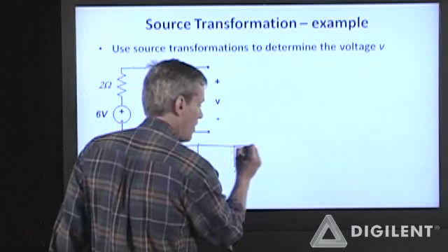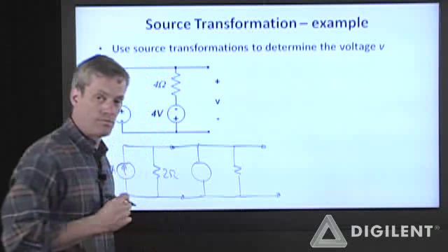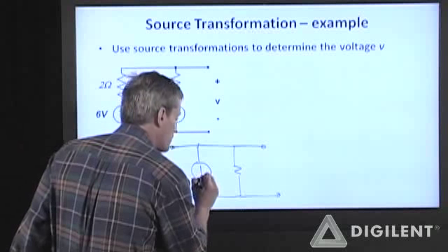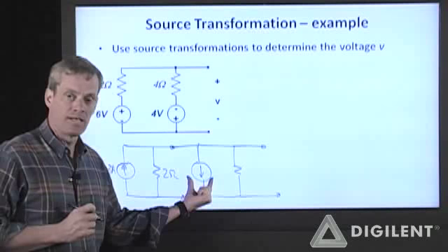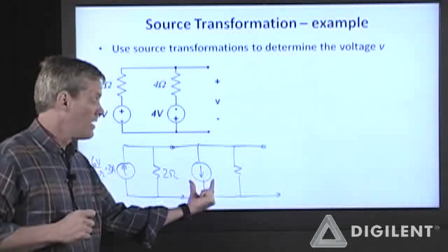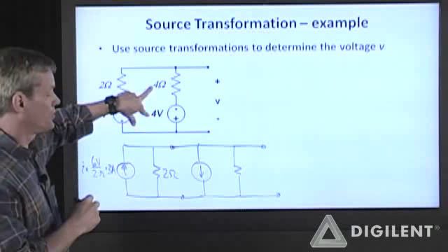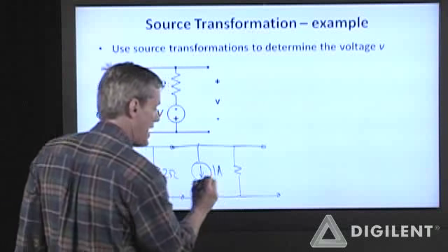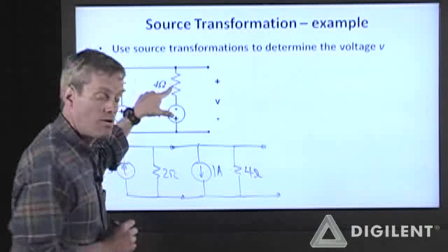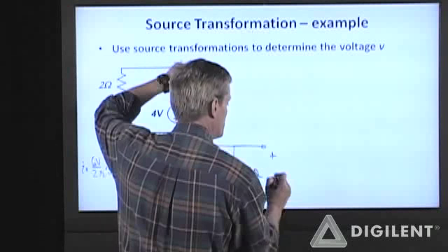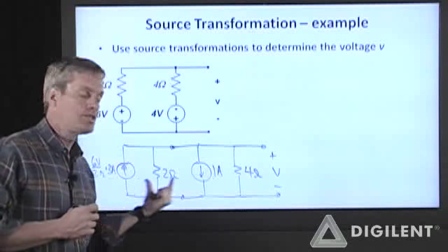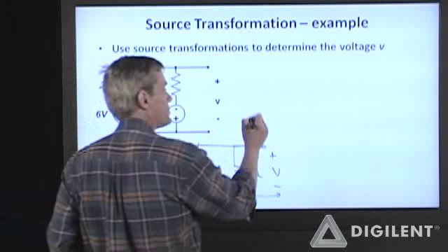These two terminals here are then these terminals. The voltage is higher here than here. This current source is therefore going to be positive downwards. This voltage source is going to be trying to push current in this direction. This current is this 4 volts over this 4 ohms, which is 1 amp. This resistance value does not change. That gives me that this voltage difference here is the same as this voltage difference. Now I can add these current sources directly and reduce this circuit.